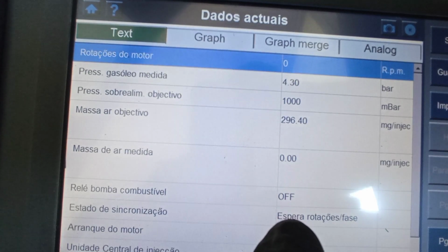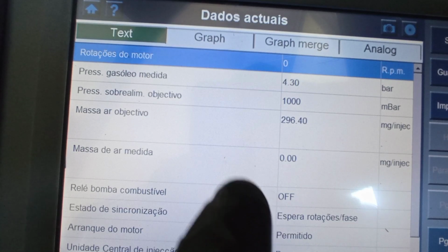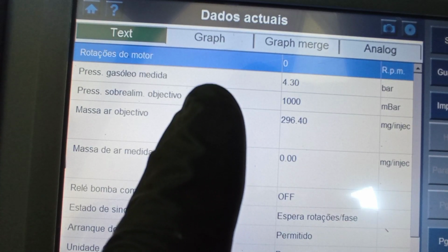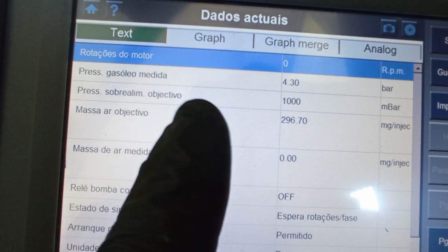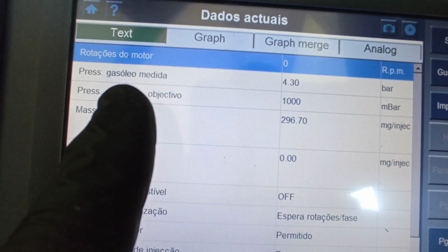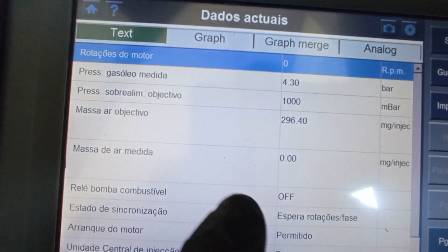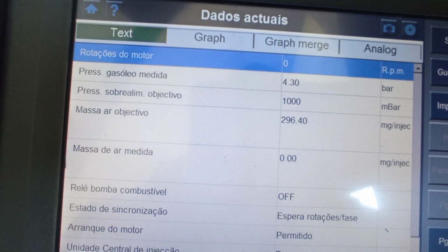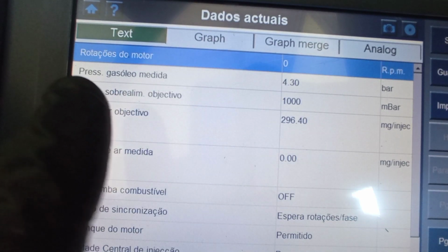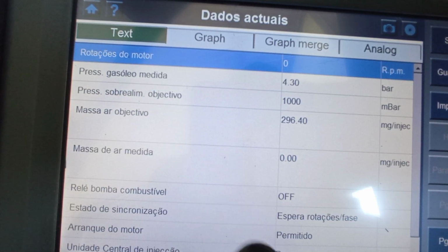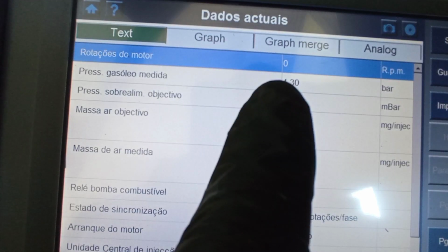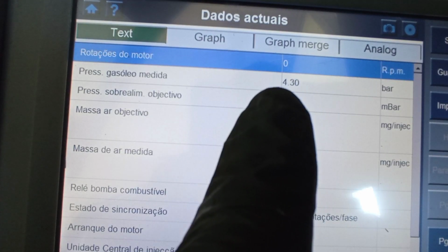Not in the perfect way, as is to be expected, but nonetheless it starts to create something resembling an RPM signal, okay? So if your RPM sensor is starting to degrade, it can actually do some magic and start to coincide both signals to create an RPM signal. So in this case, you'll be amazed to learn that, okay, I have RPM. It starts to develop very late, but I have it.